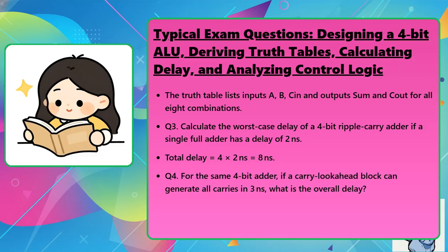Q4. For the same 4-bit adder, if a carry look-ahead block can generate all carries in 3 nanoseconds, what is the overall delay? Delay is the maximum of 3 nanoseconds for carry generation and 2 nanoseconds for the XOR, which is approximately 3 nanoseconds.